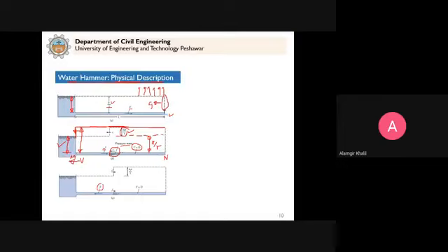Now the velocity is established, so what will be the effect of this? It will bring this high pressure to the normal. Because now the velocity is established, the pressure is reduced to establish this velocity. When the velocity is 0, the pressure goes up. Now the velocity is established, so the pressure should come down. So now a negative velocity, a reverse velocity, will establish, and it will bring this pressure down.